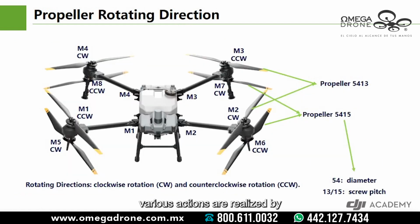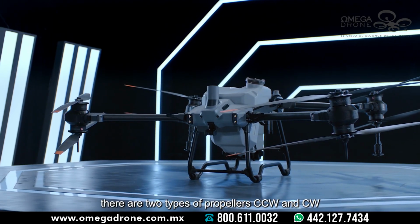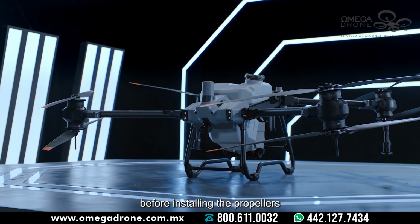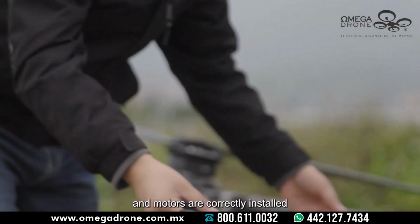Various actions are realized by changing the speed of each motor for the multi-rotor drone. For example, if the motor speed on the left is higher and the right is lower, the aircraft will fly towards the right. Generally speaking, half of the propellers of each drone rotate counterclockwise, and the other half rotate clockwise. There are 2 types of propellers, CCW and CW. Before installing the propellers, make sure that the propellers and motors are correctly installed.